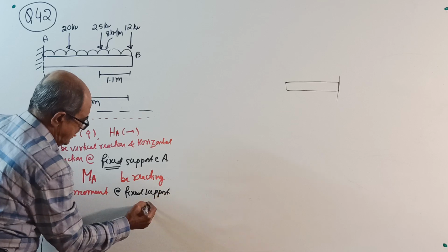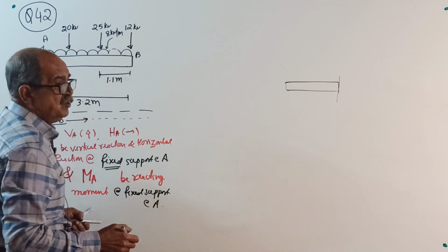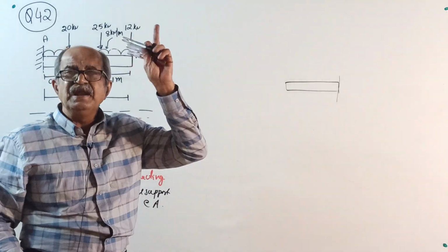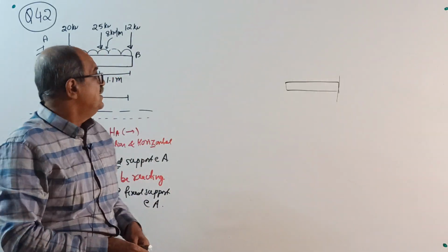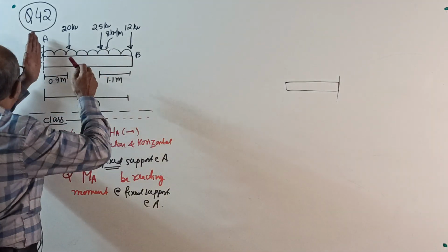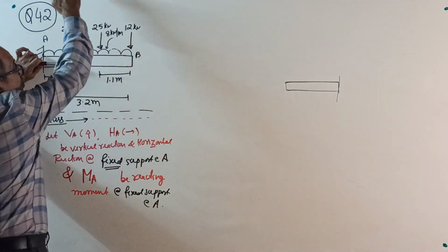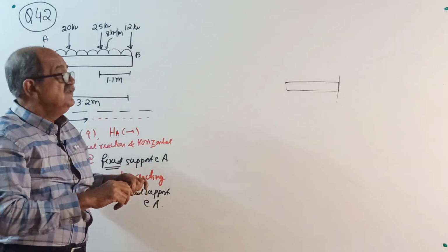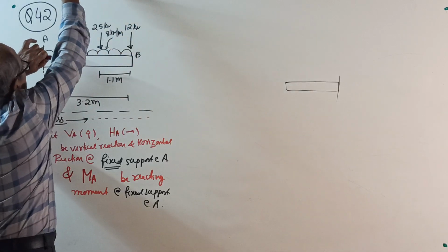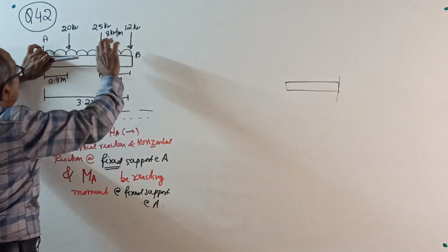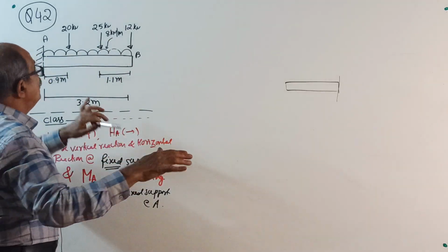All reactions at A. Now, regarding direction, I explained very clearly earlier. All you have to do is correctly observe. Come to the fixed end. Only one support is there. There is no sharing of load here. Therefore, hold here. Load is acting down, so vertical reaction is up. Horizontal reaction, don't bother now.